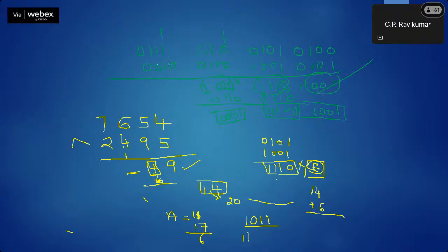So now we have 7 plus 2, 9, 9 plus 1, 10. So I'll get 1010. Once again, we have to add 6. That will make it 0, 0, 0, 0, and there is a carry. So the actual answer will be 4 plus 5, 9, 5 plus 9, 14, 7 plus 4, 11, 8 plus 2, 10, and carry. So the 0149 is what we will have. Okay, so that is what we have to implement.